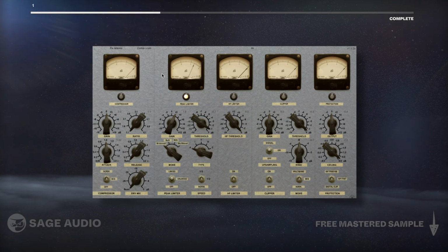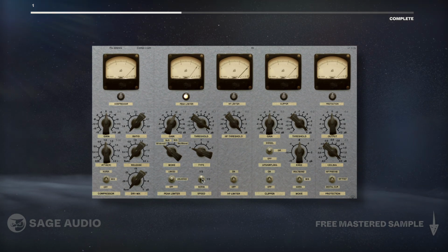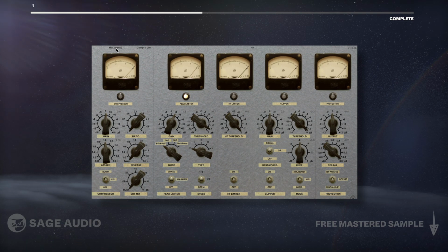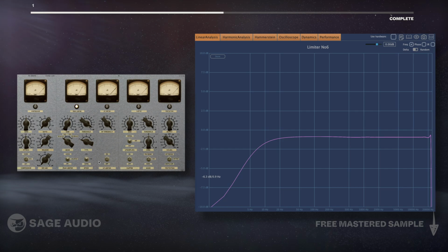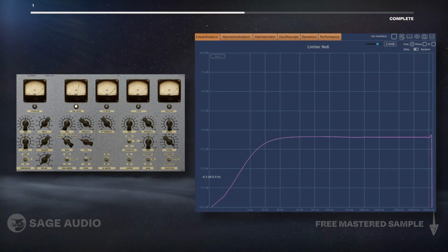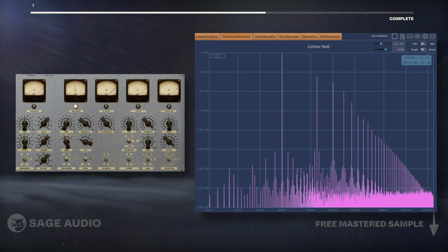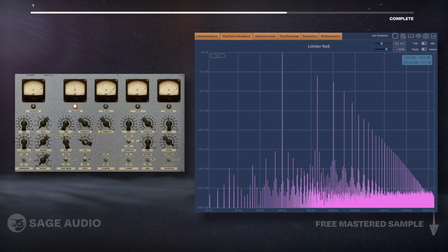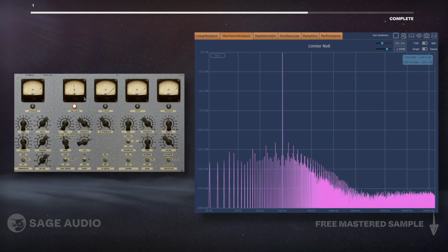We can also adjust the linking of the left and right, or the mid and side, the release speed and general behavior of the limiter, and up top we can use minimum or linear phase processing, as well as introduce oversampling. This plugin actually has a significant effect on the frequency response, with the limiter mode having the greatest impact on it. Harmonics are aggressive, and become more so when you're using the clipper. 4 times oversampling keeps the aliasing down, while the limiter type has the greatest impact on harmonic formation. Let's take a listen to the plugin.